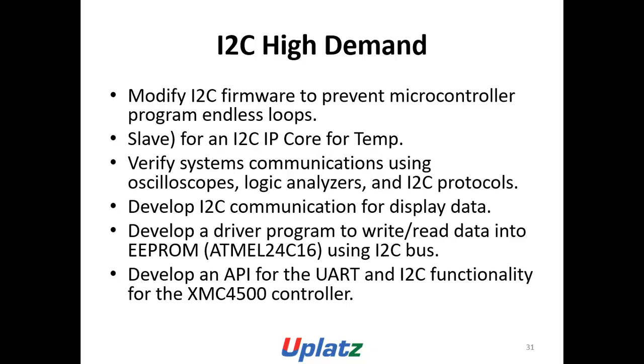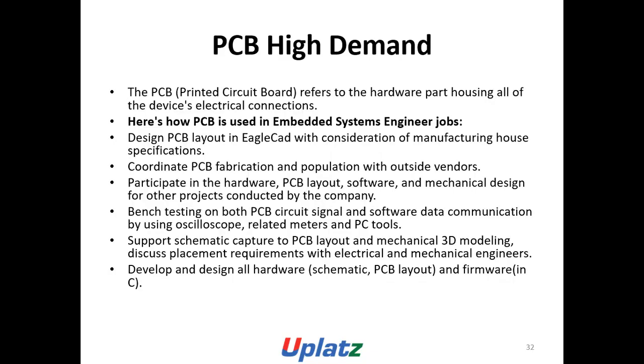Develop I2C communication for display data. Develop a driver program to read data into EEPROM Atmel 24C16 using I2C bus. Develop an API for the UART and I2C for the XMC4500 controller.